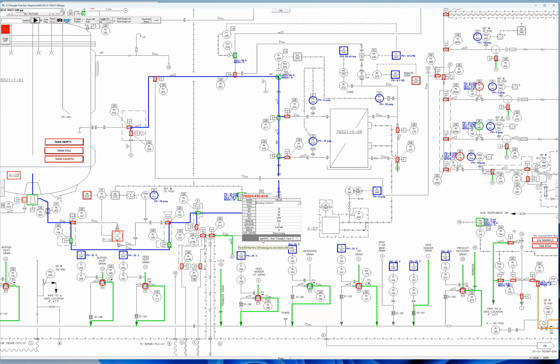So to go further, I'll go through all these buttons. The add EM button will add the EM where this CM belongs to, and essentially you can create a list of EMs that you can operate from and then generate some sort of flow path. The find button is basically for once you've got your Delta V configured and you want to find this control module in Delta V, it'll find that for you.